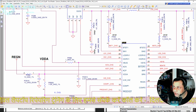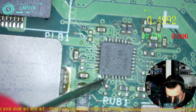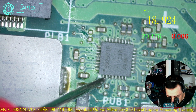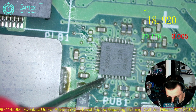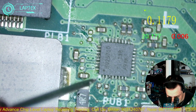So let me check it on the pin number 1. It is available, 18 volt. Also I have to check ACN, ACP. Both things must be okay. So it is the pin number 2, ACN, and then ACP. So it is also all right. Also you have to check the impedance between both ACP and ACN.